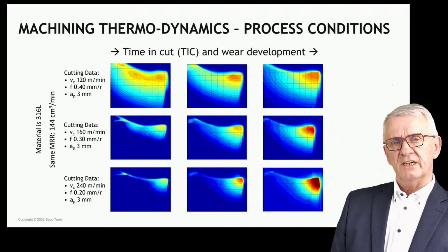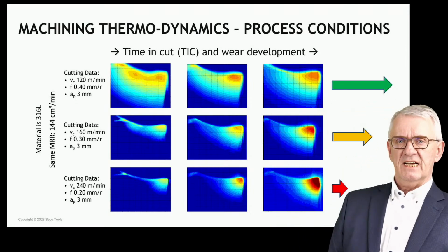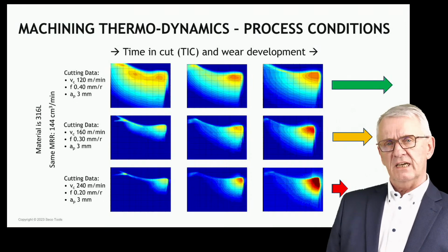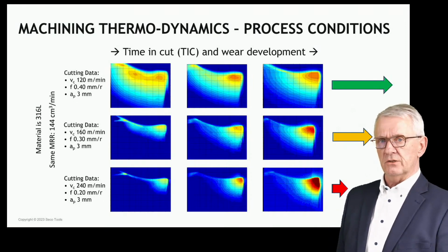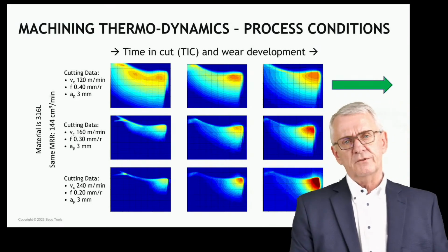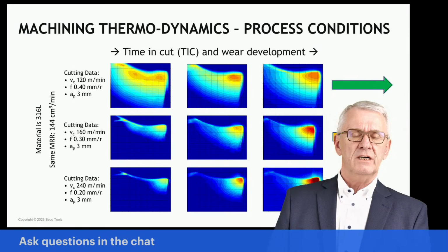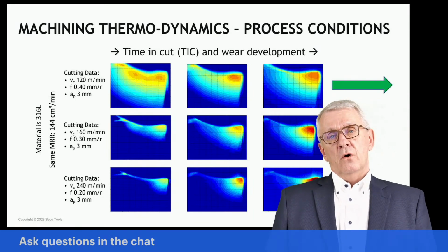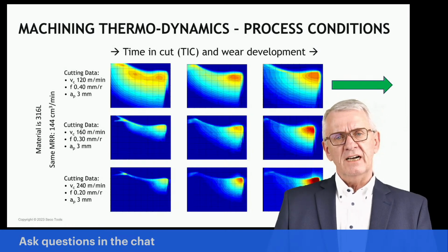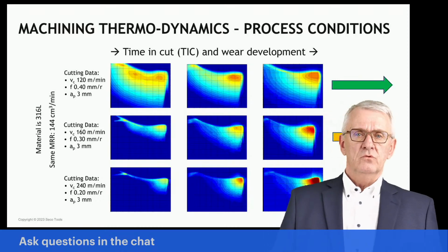So you have here 1 cutting tool, 1 application, workpiece material type application, 3 combinations of cutting conditions. And what you see is that in the top, you can continue to cut with the cutting tool with no worries. You don't have a dangerous situation yet. In the bottom, you went now in a situation where perhaps it's better to change the cutting edge. And one could say from left to right, you have kind of tool life limitations. In the bottom, you already reach end of tool life. You need to replace the cutting edge before you continue, while on top, you still can continue to use this cutting edge, no worries. So heat and temperature are kind of a relation maker between tool life, tool costs, and metal removal rate.